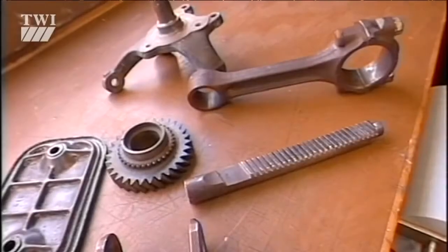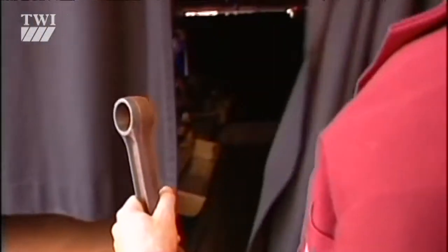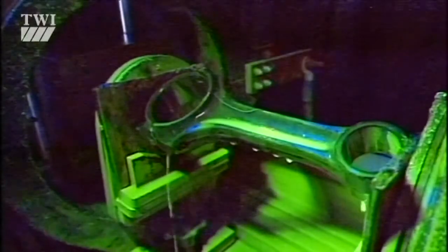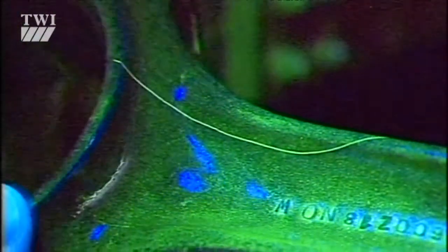With the fluorescent technique, we coat the component under inspection with a fluorescent medium while the part is magnetized. Under a fluorescent lamp, discontinuities or defects show up vividly as bright green. It's a more sensitive technique than the color contrast method.